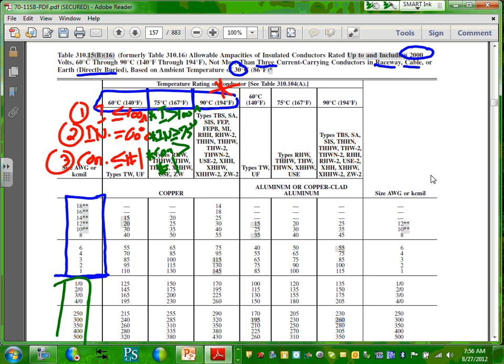75. Can I get you to understand these? That will help you go through the whole year. This is the division between basically the 60 and the 75. Very, very important to know that. Repeat: piece of equipment less than 100 amp, you have no idea what the lugs are, you're going to default here. Insulation 60, you're here.